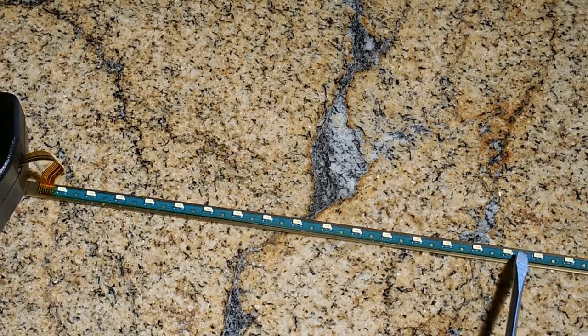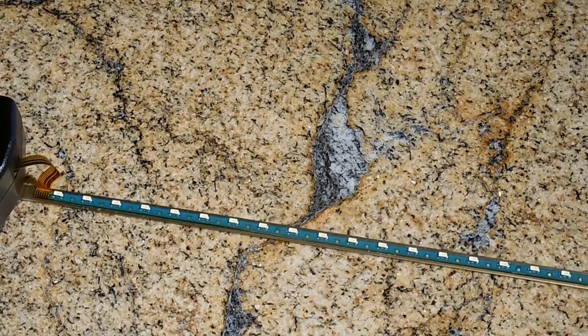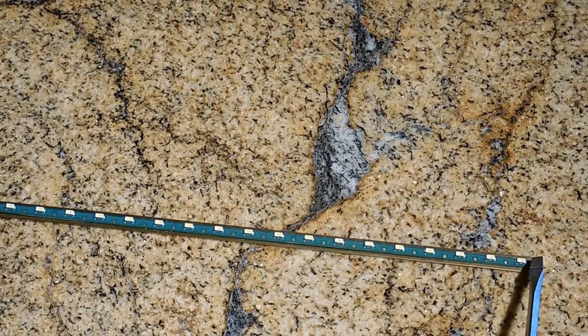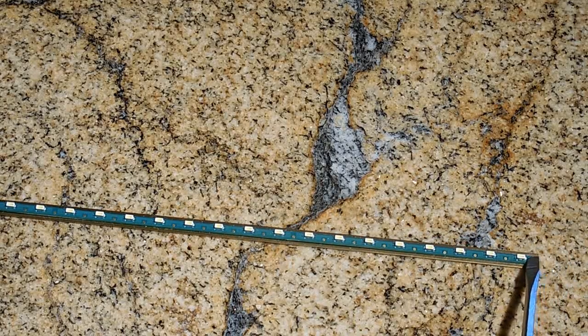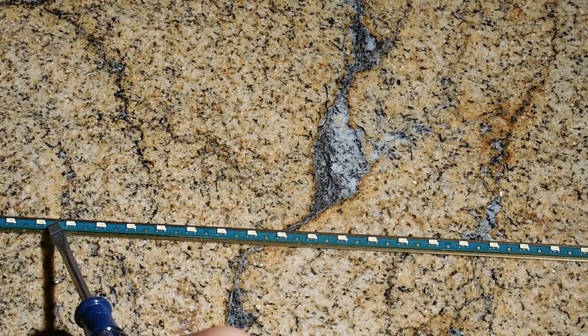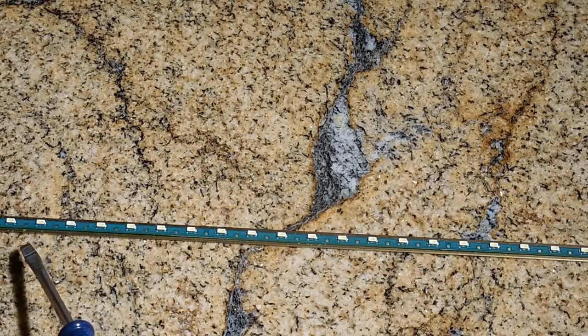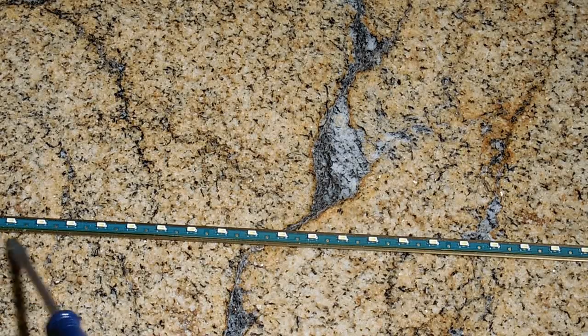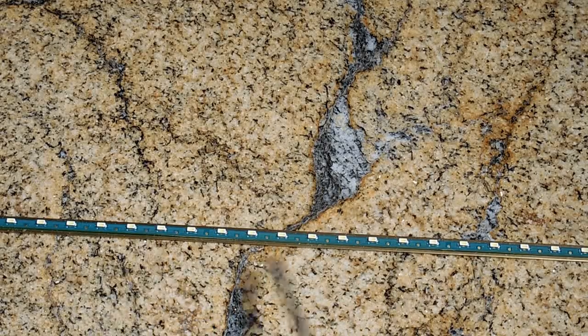Then you got the same thing again here, positive, and then you got 1, 2, 3, 4, 5, 6, 7, 8. And this right here is the negative again. You're going to get all the negatives, tie them together. You're going to get all the positives, 3 of them in my case. If you're using the full strip, you're going to have 4 positives, 4 negatives. You're going to connect them in parallel, and you're going to be supplying approximately 25 volts to all of those LEDs in parallel. You have 4 sets of 8 at 25 volts.